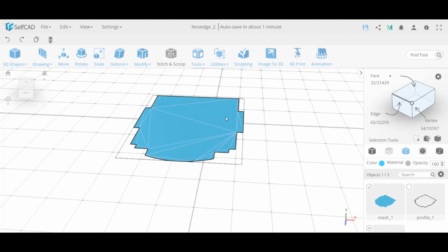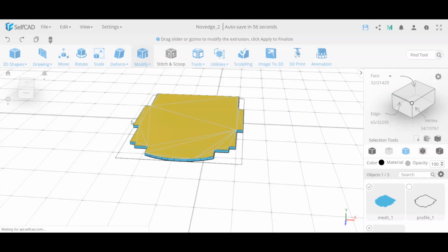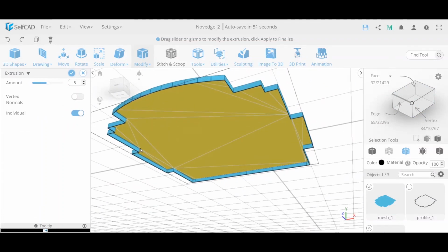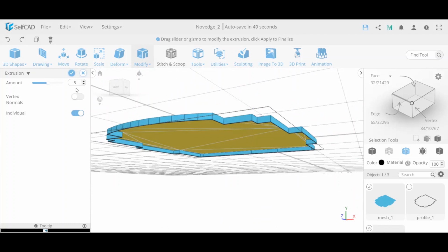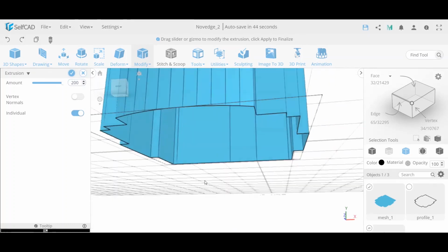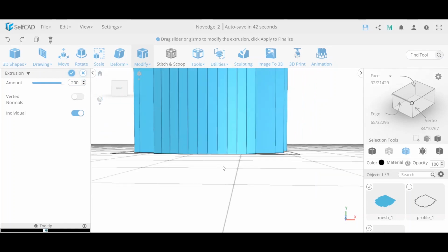So it's better to first fill them in 2D and then extrude. If you do extrusion, this will move up the face, and it will leave you the bottom closed. So, for example, I'm going to type in 200 and fill it in that way, you can see it has this hole. And in some cases, that's what you want to do.